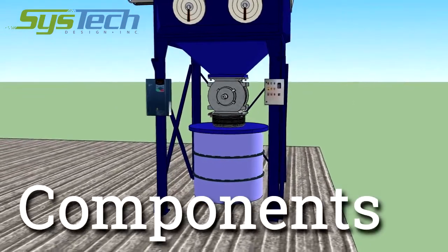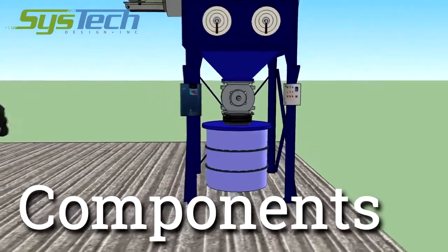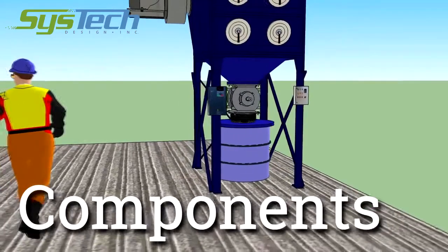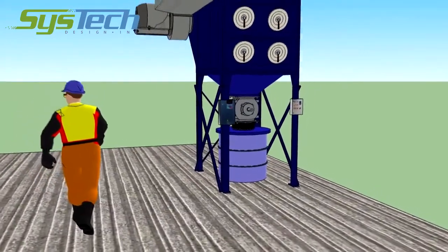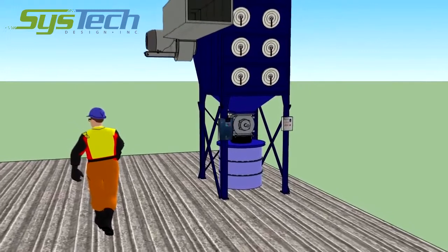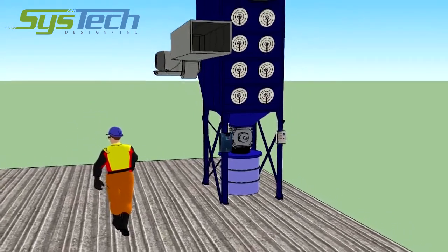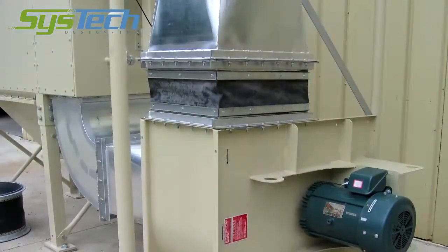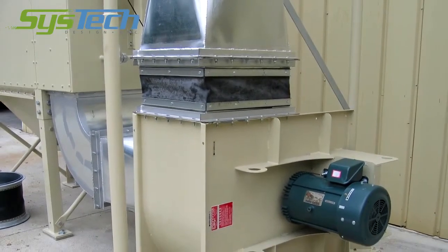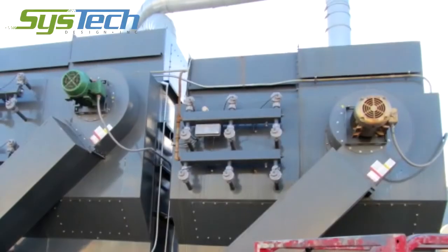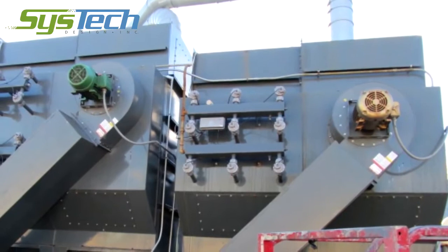The sixth C is components. There are many optional components to an air pollution control system such as fan silencers, rotary airlocks, compressed air filters, and flex connectors. A frequently misapplied component is the fan noise attenuation. Typically, the rule of thumb used for fan attenuation is an 85 decibel silencer for an industrial environment.